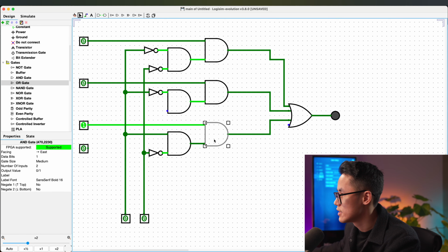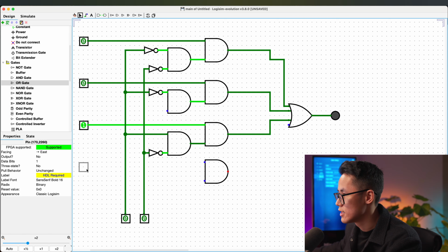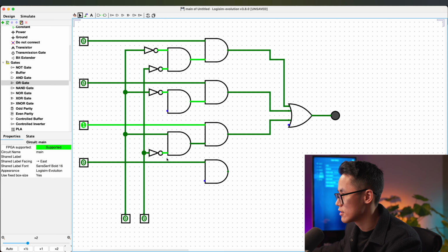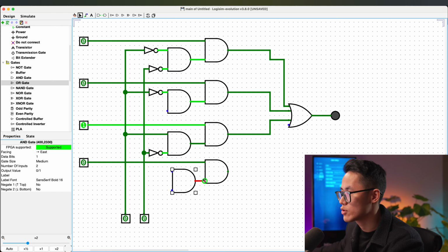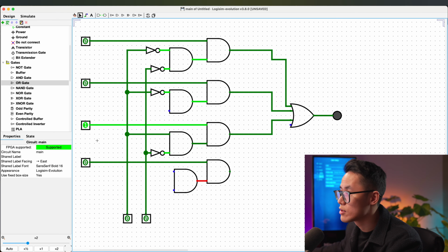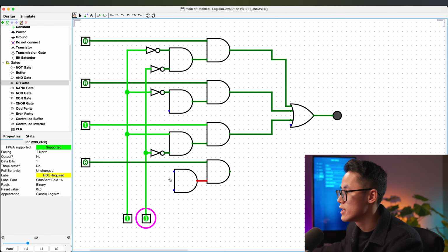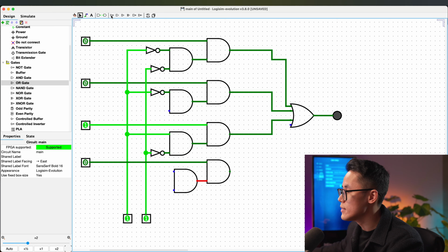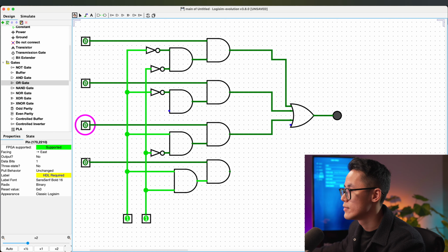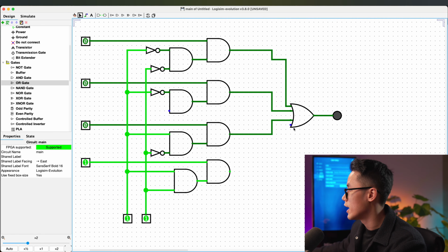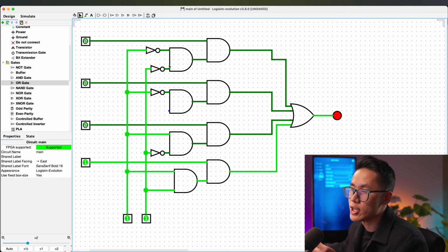I'll create the last one just to finish the work that I started. Yep, this connects here. Need to use an AND gate. Make sure this connection is on. And what is the select bit? If I want to control this input, it will have to be 1 and 1. Okay, so when it is 1 and 1, I don't have to make it go through any NOT gates. Just connect it straight away, like that. Okay, so now this one on, I can connect it to here. So now I finish it.